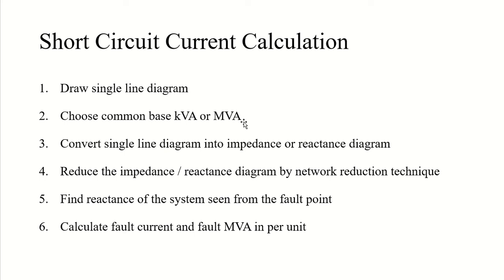And the steps involved in three-phase symmetrical fault analysis will be six in total, as I've mentioned in this slide here. So firstly, we will draw the single line diagram of the components, right? We will include each and every component of my whole network. We will take its ratings and resistances, reactances. We will take everything into consideration of whatever component we have drawn.